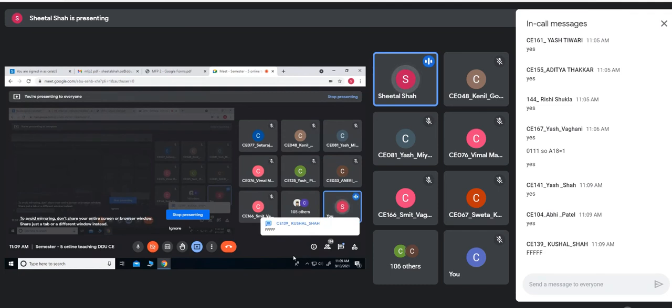FFFFF would be the ending address. As we know, FFFF0 is the address while we reset the processor, and that contains some program. That program should reside in the ROM, isn't it? If it is in the RAM, that program would be lost. So it should reside in the ROM, and hence FFFF0 should be the ROM address.